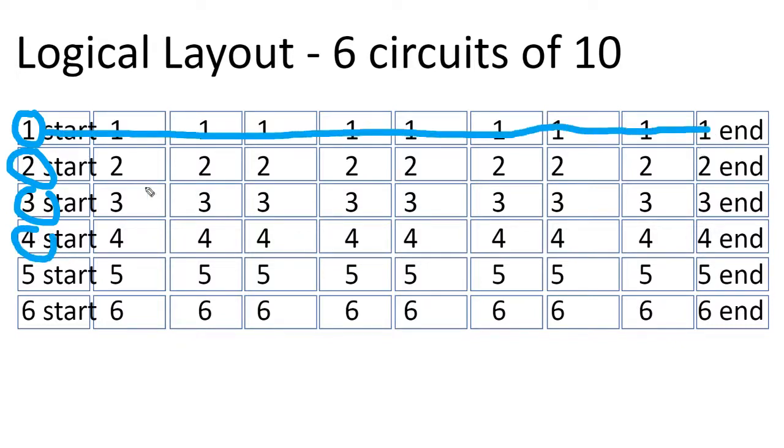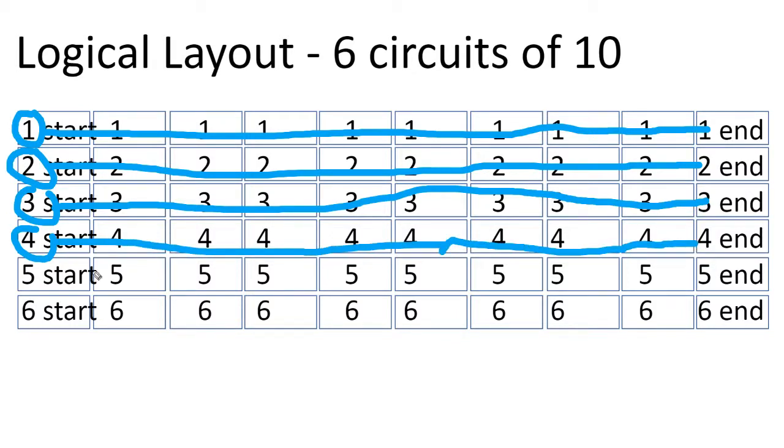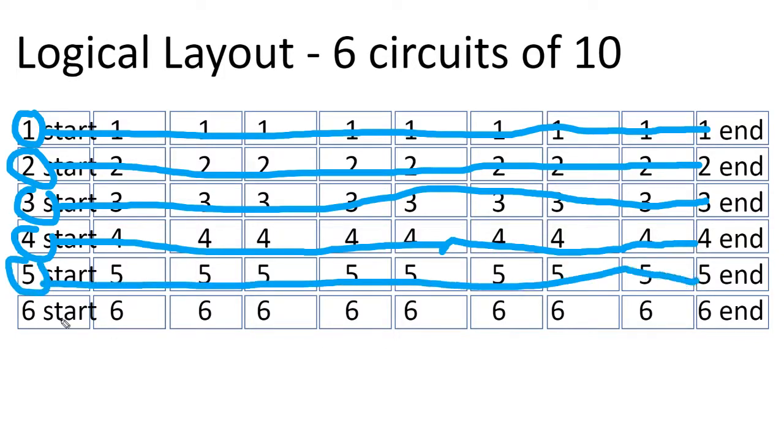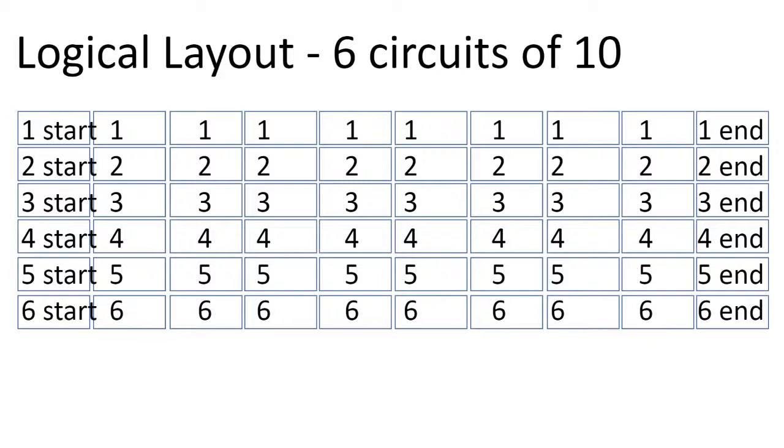There are two approaches to circuit layout. I think it's best to go for a simple, logical circuit layout, even if it means using more circuits than necessary on the roof, if those circuits start and stop in logical places. For example, starting a circuit on one side of the array perimeter and ending the circuit on the opposite side, moving across the solar array in a straight line, is a logical, straightforward circuit layout.